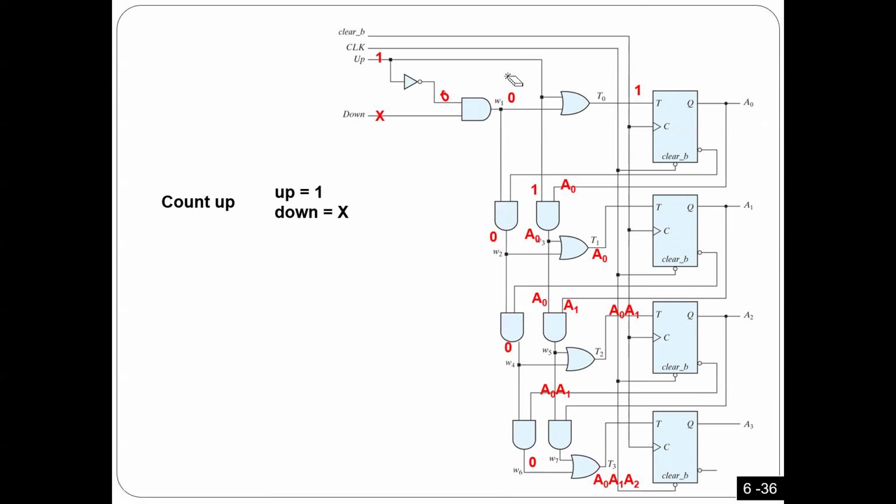Okay? And now, because this one is 1, this is how you can activate or deactivate. How can you do that? Very simple. If I make this 0, everything here is cancelled because it's an AND. If I want to cancel this branch, I put 0. Put 1, you activate. 0, you cancel. If I put 0, 0, both of them are going to give you 0. No change.